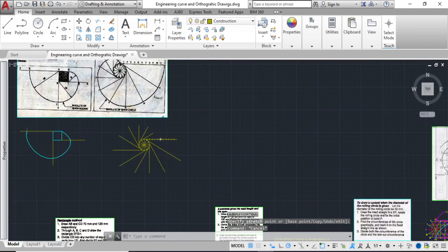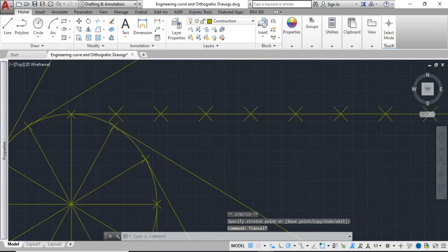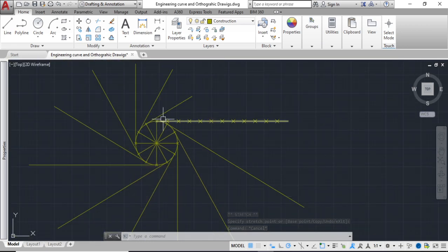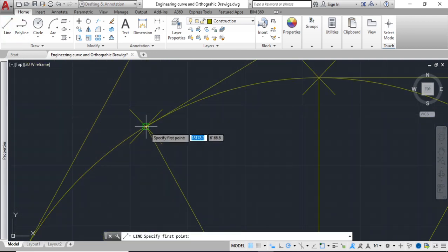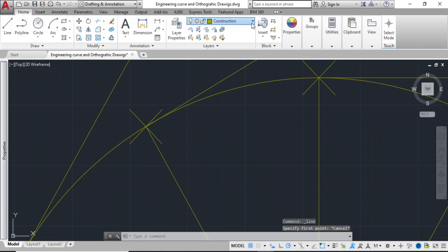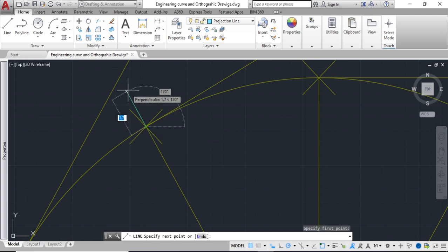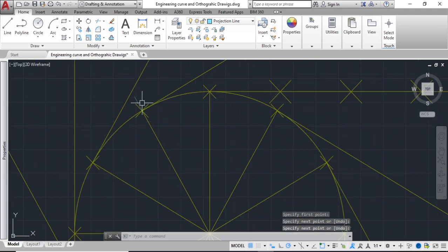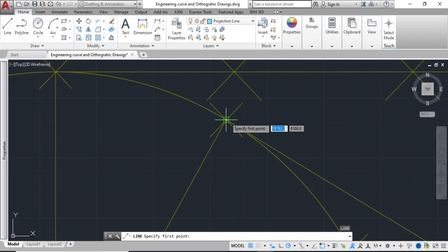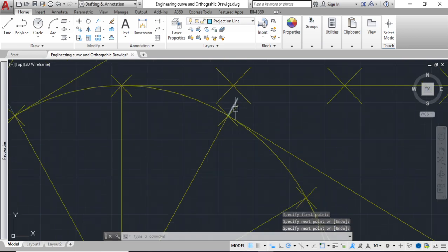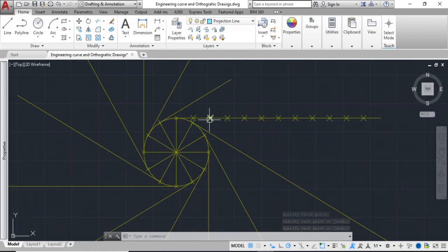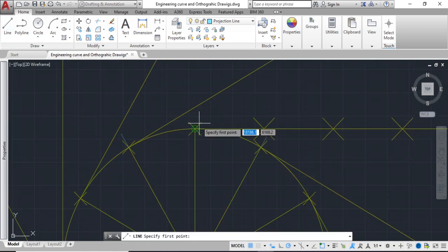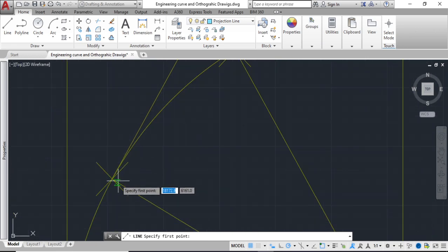Right, so I already did all my lines. Next thing I want to do is to plot them. So how I go about doing this now is to offset, the versatile function called offset. So I want to use lines that I can delete later. So some phantom lines, and I go ahead and draw them in, right? And I go draw them on all of my lines. Why? Because I'm going to offset this to the measurement of from 1 to whatever it is. So draw some lines.